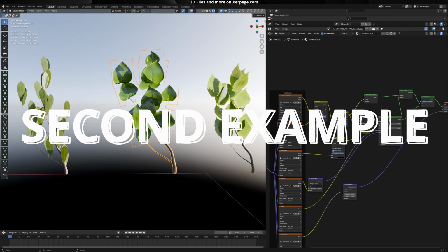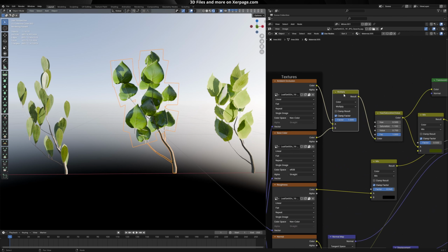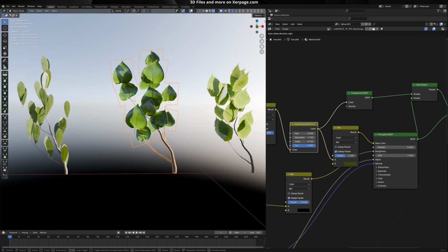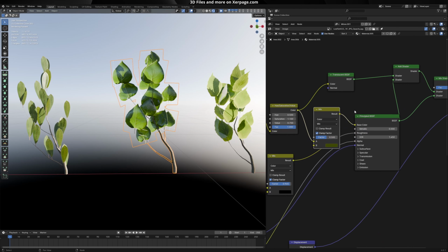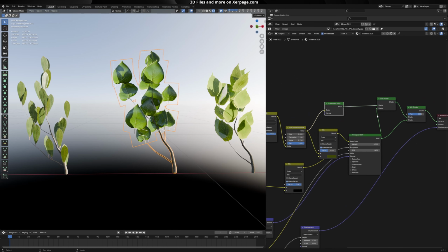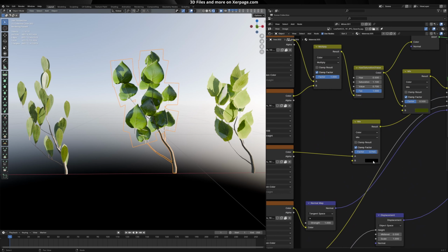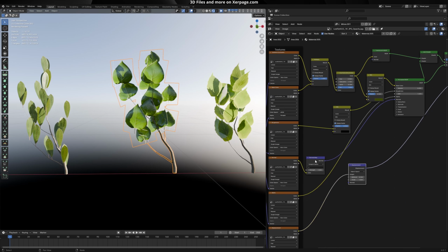For this other texture, I've used the same material of this render. You can find the tutorial on the channel if you want. There is a multiply node between the ambient occlusion and the base color set to 1. After I use hue saturation value with value to 0.7 and saturation to 1.1. A mix color node with this exact color. The hue saturation value is also connected to translucent that, like before, is connected to another shader and a mix shader. This time the factor is set to 0.8. The roughness is set almost to 0, as you can see, with a mix color node. And this time I've used both the displacement and the normal map.